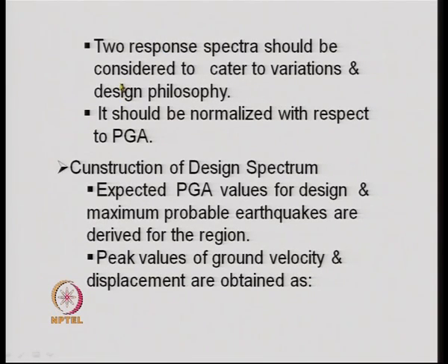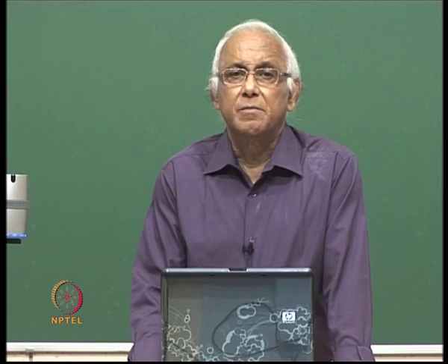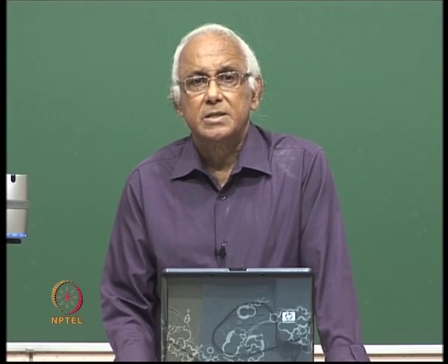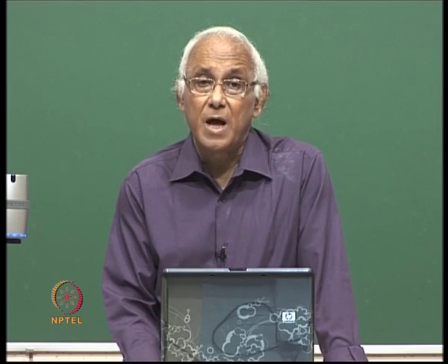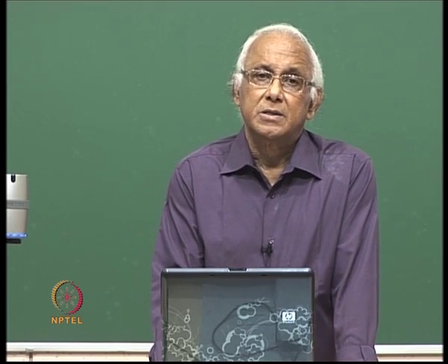Next, two response spectra should be considered to cater to variations in design philosophy. Now, the design philosophy of earthquake resistant design is that we design the structure for a design response spectrum and see that the structure can survive in the extreme earthquake condition. That is, there will not be a complete collapse of the structure in the severe earthquake.